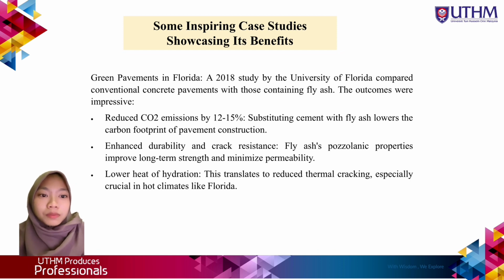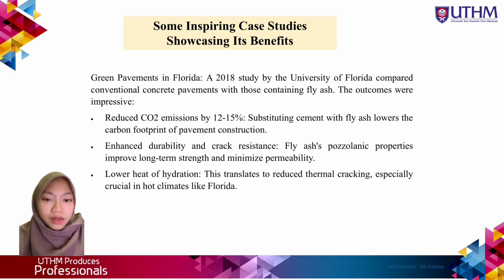The outcomes were impressive. First is reduced CO2 emission by 12 to 15%, since substituting cement with fly ash lowers the carbon footprint of pavement construction. Second, enhanced durability and crack resistance, as fly ash's pozzolanic properties improve long-term strength and minimize permeability. The last is lower heat of hydration, which translates to reduced thermal cracking, especially crucial in hot climates like Florida.